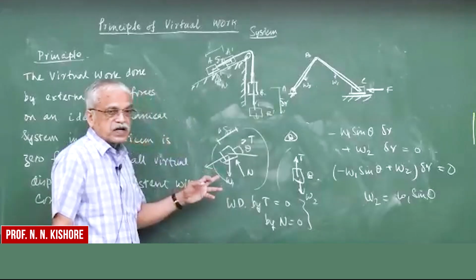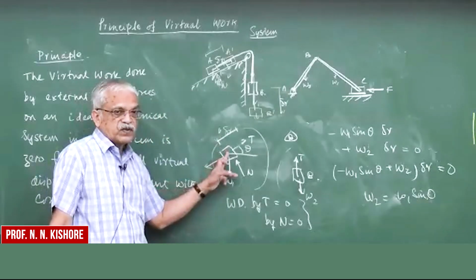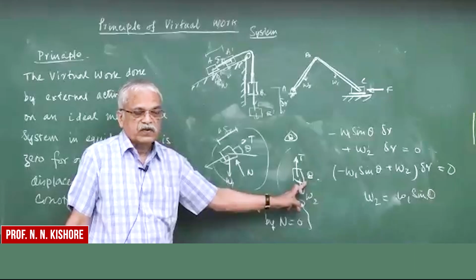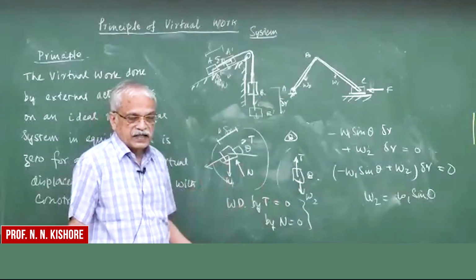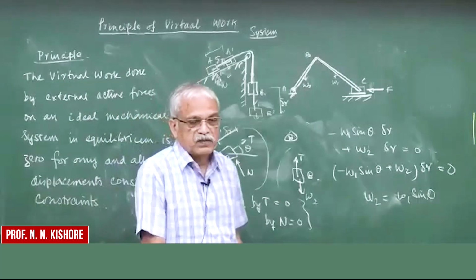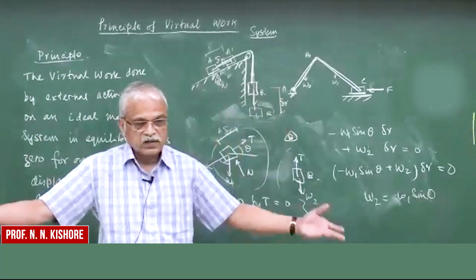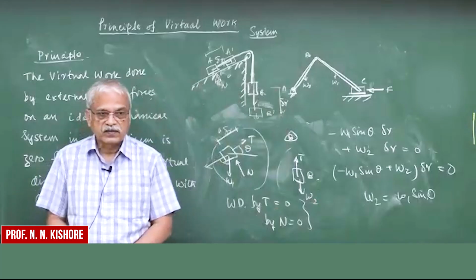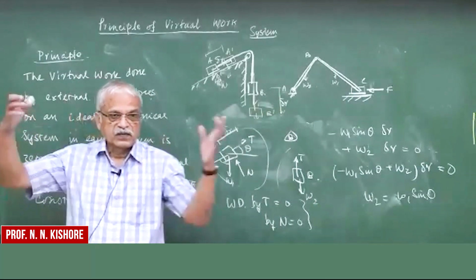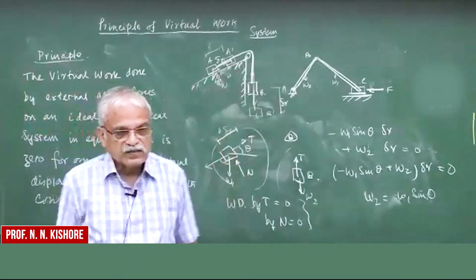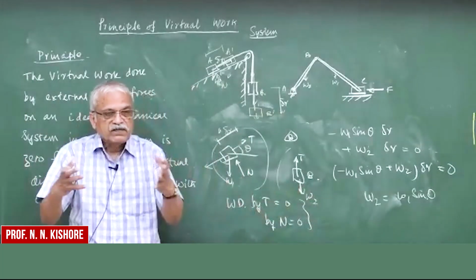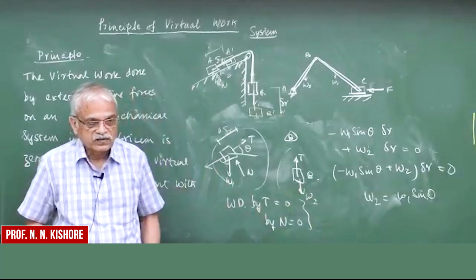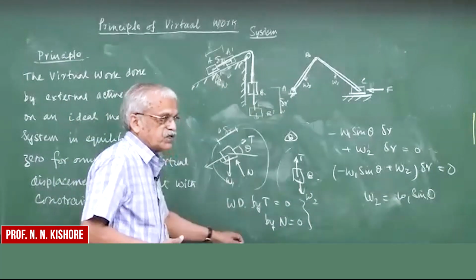Otherwise, you would have to analyze this free body diagram and this free body diagram, eliminate T, and then calculate the relationship between W1 and W2. Now you can see the power of this principle, that for a very complex system of forces you can get a very, very simple equation. It's really a very beautiful principle.